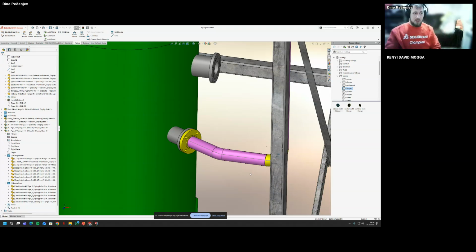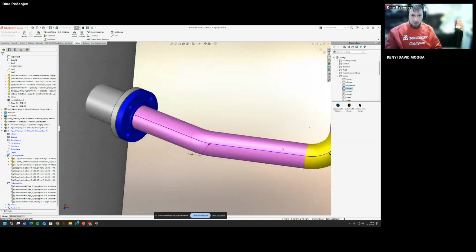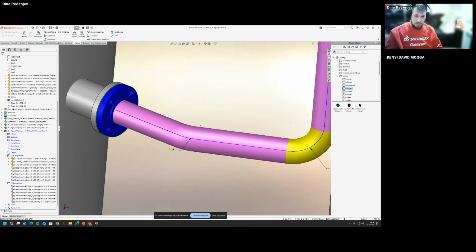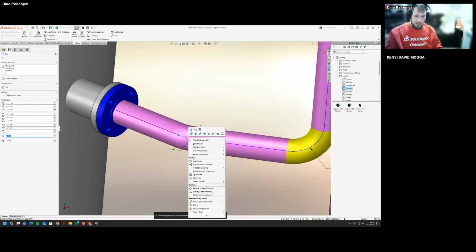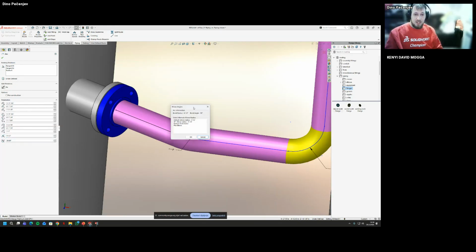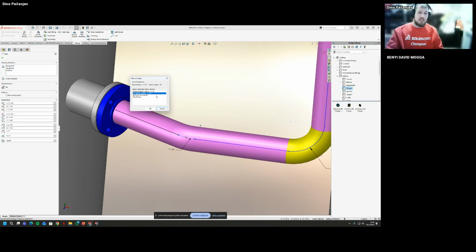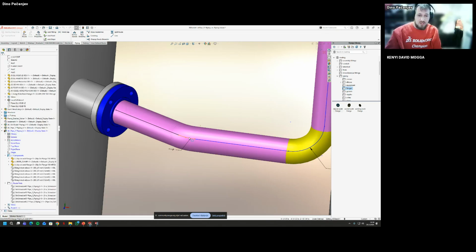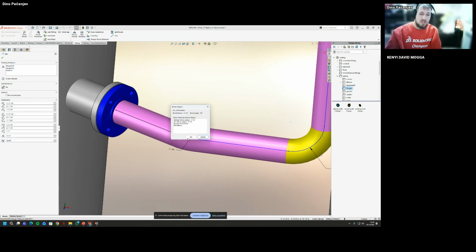So let's say the design changes and I want to set an elbow here. I will just right click, edit route, right click on the fillet, and it's actually here, elbow angles. And here I can say 45-degree elbow radius, I can use it, but this is not 45 degrees, so I'm just going to set cancel. Or if I want to remove the form bend, I could do it with this option. So once again, right click, elbow angles, and this prompt window appears.